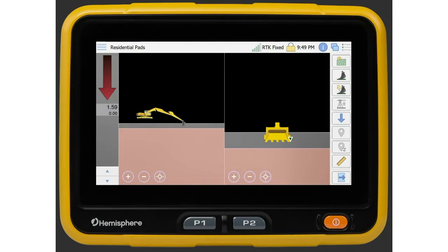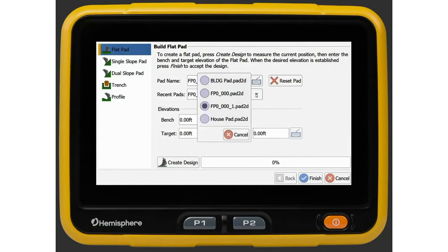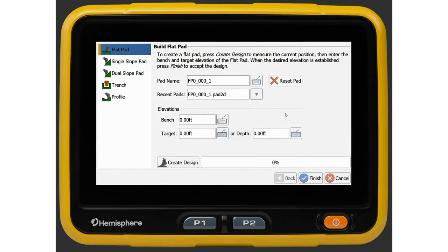When we go into the menu and grade 2D, you will see a list of icons on the right side. The very top icon will allow us to choose what type of 2D entity we would like to build. Every option will ask for a name and will also save the associated settings to that name so you can easily select them for later use. These are configured similarly to field design. For the sake of time, I will only briefly cover them.